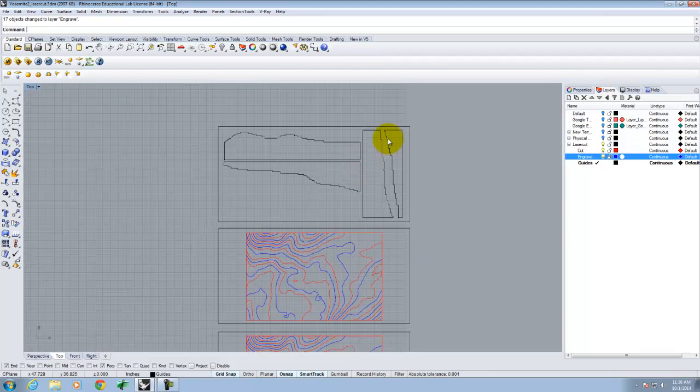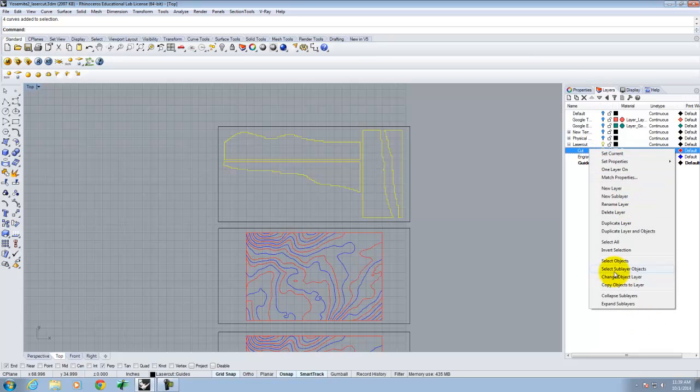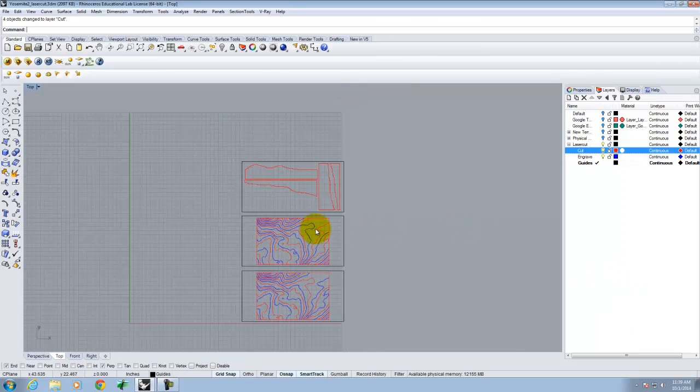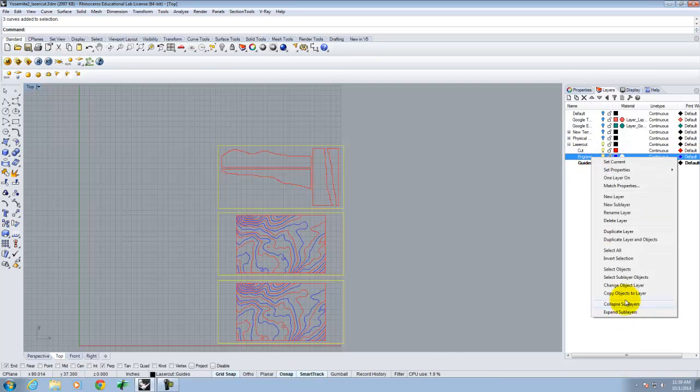So up here, on all the sides, those all need to be cut out as well. So I'll take each of those and I'll change those to be on the cut layer. And now those are on the cut layer. These black pieces are guides. You could make them one of the colors. Sometimes I do just so that the laser cutter, if accidentally it's misaligned, it won't go through and rasterize these. So we'll go ahead and select those and we'll put them on one of the layers as well. I'll just do it on the engrave layer.